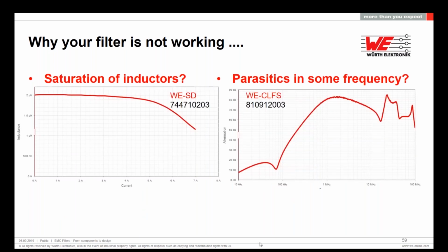Saturation of the inductors: if we have differential mode inductors, they will at some point be saturating. So we need to take a look at which inductor we are choosing and that we are always below the saturation, so our calculations are as close as possible to reality.